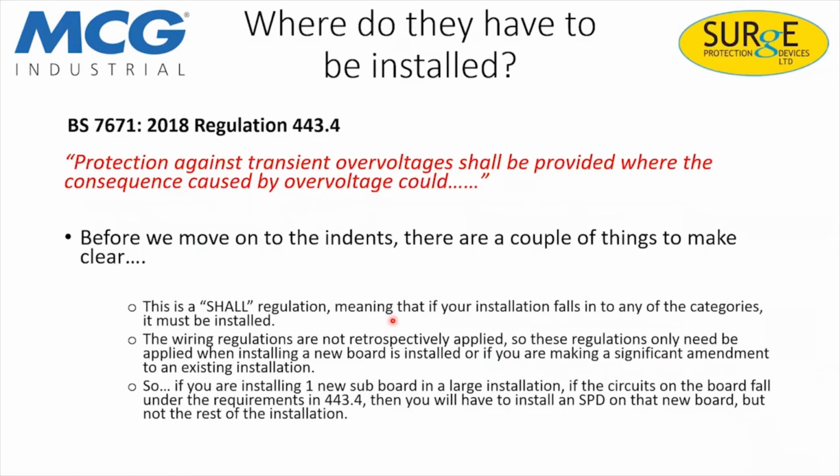So we'll start having a look at the 18th edition regulations. So 443.4, protection against transient overvoltages shall be provided where the consequences caused by overvoltage could. Before we move on to the indents, there are a couple of things we need to look at. This is a shall regulation, meaning that if your installation falls into any of the categories, it must be installed. You can't say your client doesn't want it or decide it costs too much money. It needs to be done.